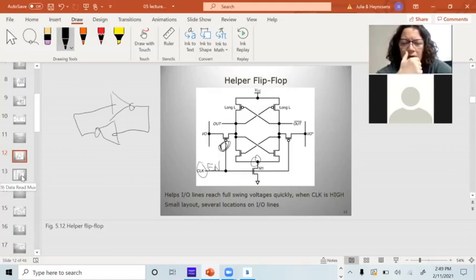You can design a microcontroller in an FPGA. They're really powerful, and all you're doing in an FPGA is standard CMOS. But when you want to drill down to circuits like these, they are non-standard circuits. You can't make these with HDL. They're a combination of standard CMOS, pass transistor, dynamic, and analog techniques, with diff amps, and another category which I call what the heck, it works.